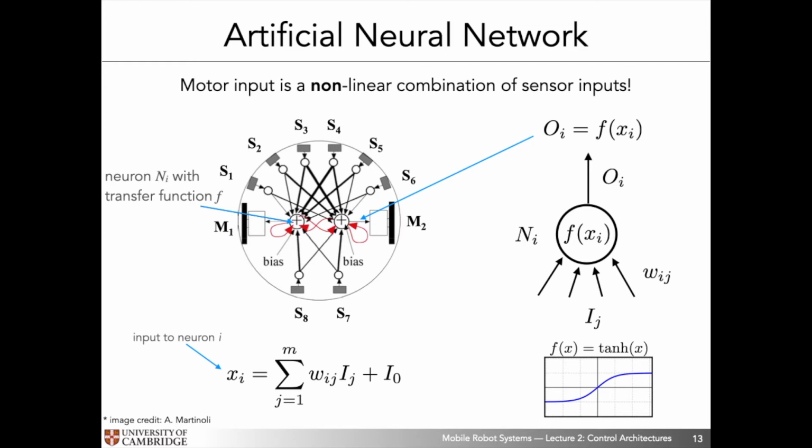So what is the nonlinear transformation to be? Well, there are many options for this, and one example, the one that I'm showing you here, would be to take the hyperbolic tangent, which functions similarly to a sigmoid. It goes from -1 to 1. And this is interesting because you can then scale or normalize the support on the y-axis by the maximum wheel speed, for example, right? Now, this kind of completes the full neural network architecture.